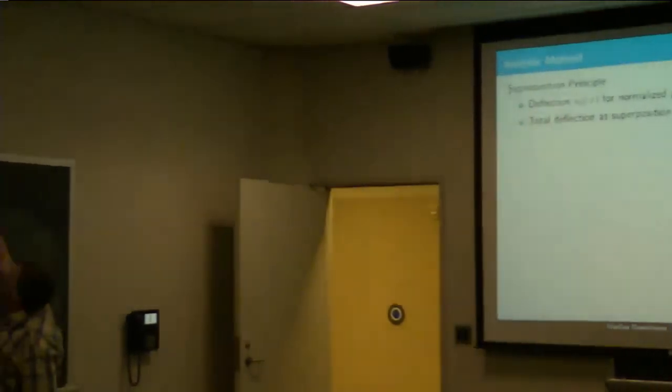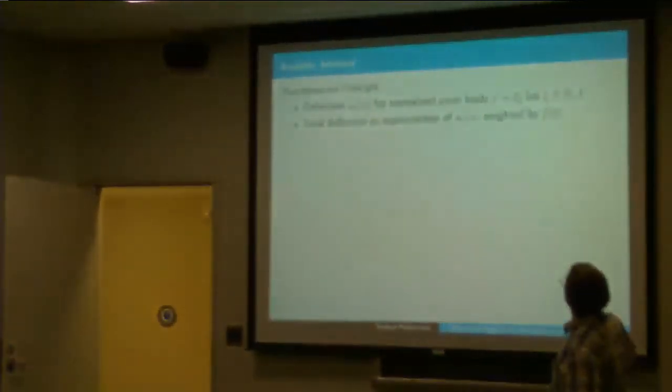That means something like, you imagine there's one unit of weight. Think of 1 kilogram. It doesn't matter what the units are. But it's a unit weight, and then the total deflection would add up all these elementary deflections weighted by the actual weight that is applied at this point psi.